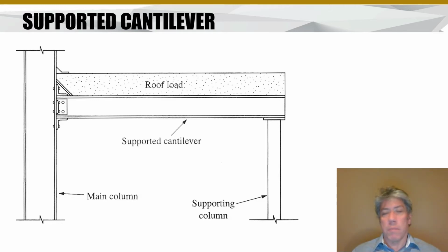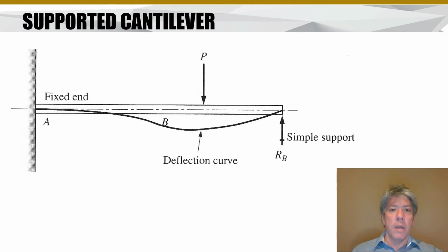But of course we can build this, right? And then we can put the roof load on top of it and measure the load. So certainly nature figures it out somehow. And the key is to understand that deflection is what helps us, okay? So that's why I keep going back and saying intuitively, here's the curve, the deflection curve, for that loading scenario. With a simple support out at the end, notice that RB has a line through it indicating that point can't move up and down. That point has to remain where it's at, and that's really the key to solving these statically indeterminate beams.